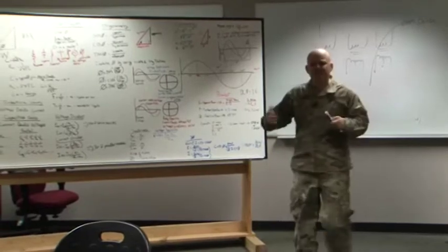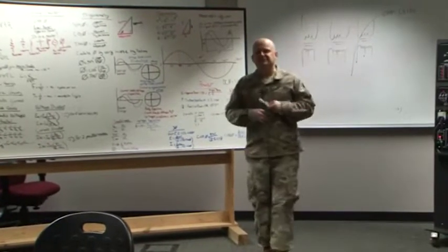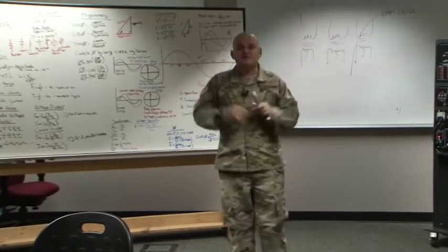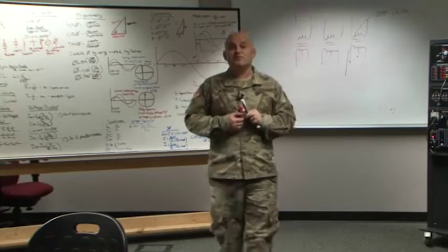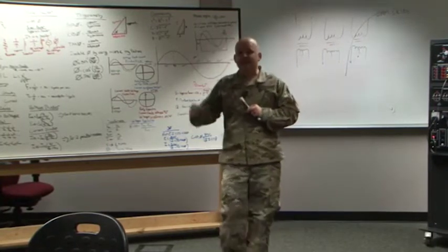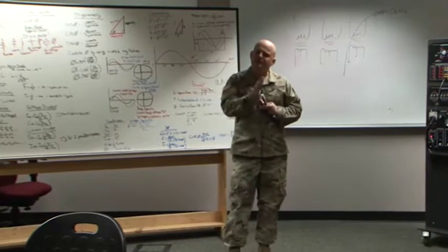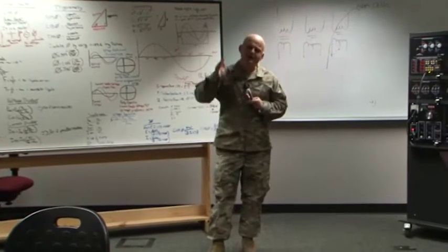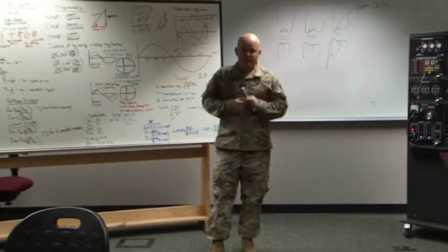And then for the last thing, we just say, hey, let's put all this together. Let's bank a bunch of these together, and let's build a three-phase transformer bank, and let's play around and see what our voltages are so we can validate the science. And again, that 30-degree offset that's created between certain configurations, and why 1.73 is a thing, even in transformers.